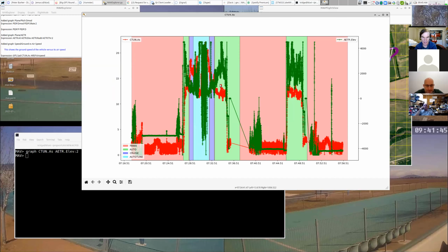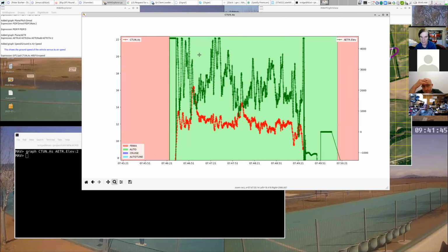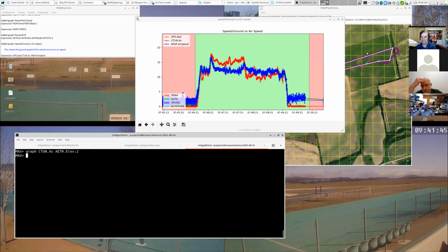So in this auto mission, it's a bit hard to tell because that's the auto tune. We'd have maybe this part of the flight, we might be able to tell something. So at lower speeds here, he needed more elevator, and at higher speeds the elevator was down. It's always way high, but it's less elevator at these higher speeds. But it's a bit hard to tell because it's quite noisy. I can see the elevator, and you expect a stable airplane will require more elevator to fly at a slower speed, and less to fly at a high speed.